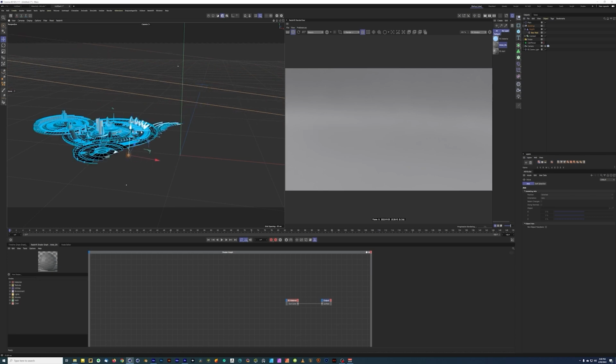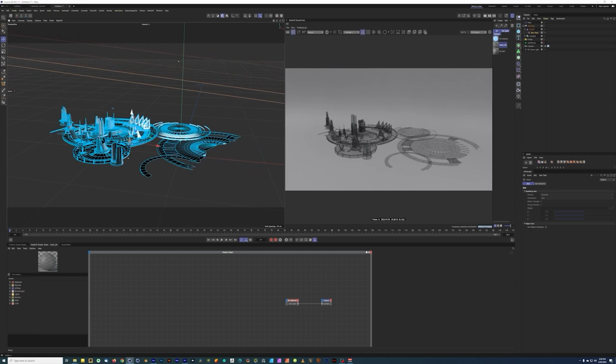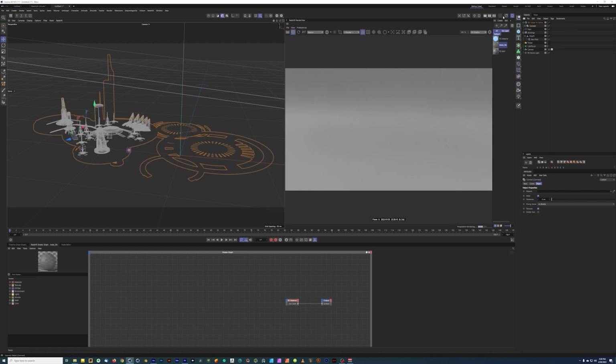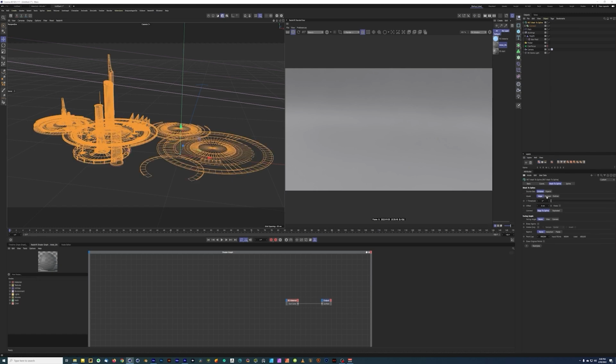You can make different kinds of renders depending on what you want to do, putting different colors or shaders or effects on that. And then what I did was I used a plugin from Chris Schmidt at Rocket Lasso, a plugin that I like a lot called Mesh to Spline, and I made the geometry splines. So I'm just going to drop this object into Mesh to Spline, and it makes some of it splines to start off with, but because this is such a dense model, I'm just going to click override, and my computer has no problem turning all of that into splines.